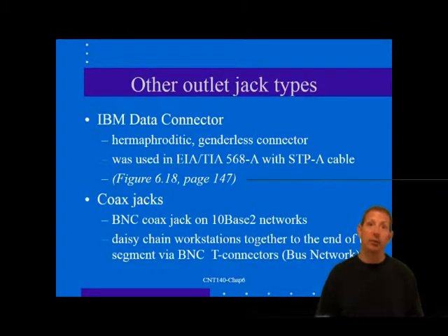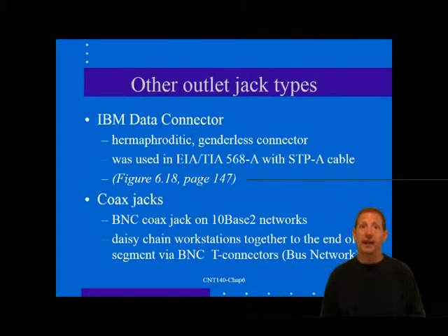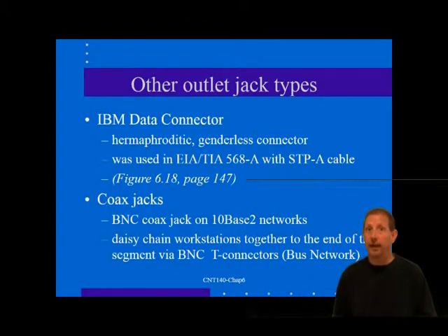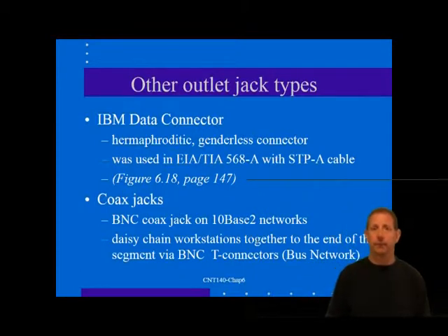The cover plate is attached to a standard outlet box, and the STP-A cable is then terminated directly into the outlet connector. Versions of data connector faceplates are available that contain both data connector and one or more modular jacks. The data connector and STP-A cabling system is a robust system that offers certification up to 300 megahertz, 3 times the current maximum frequency specification of standard UTP systems.